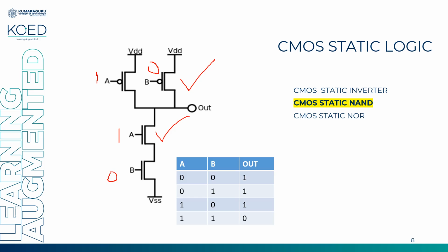I have obtained. Here, practically speaking, my 1 will not be obtained as output. You have little degradation in your output, practically speaking. The reason is this transistor is in on condition, so if it is 5 volt, at least 1 volt will be leaked out of this node till this point. Only till this point, because again B transistor is an open switch, it will not move any voltage from here.